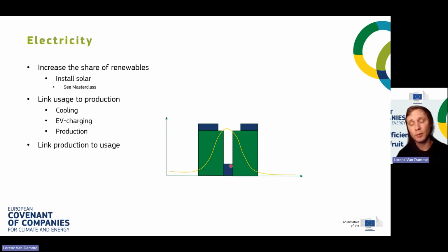How do we do this? We do this by, at this point in time, increasing the temperature set points for our cooling system, meaning that it will cool less because it takes a while for the site to warm up. And then during the lunch hours, we will reduce the set point below the original one and try to use our cooling system as much as possible to cool down everything while we are not using the electricity for production,